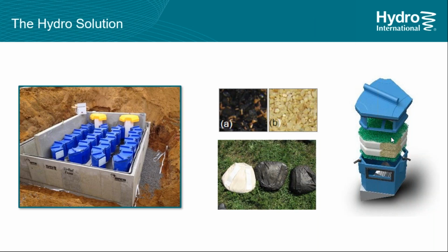So there's no winches, there's no special lifting gear. It's designed that someone can hold a pack in each hand, hand them to the surface, roll them to the surface, whatever you decide to do. And then as far as disposal, the vacuum truck or any trash can accept the spent media bags. There's no hazardous waste associated with them. So it's a quick and easy cleanup. And that was Hydro's first version of the Up-Flo filter, focusing on maintenance.